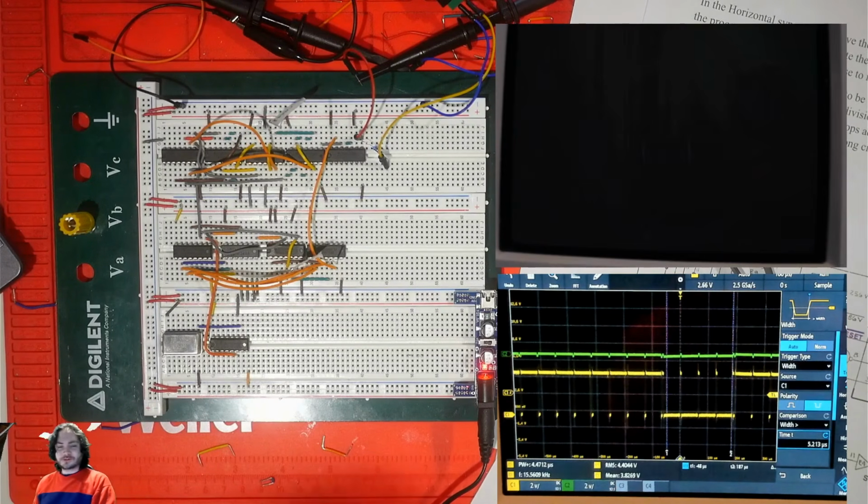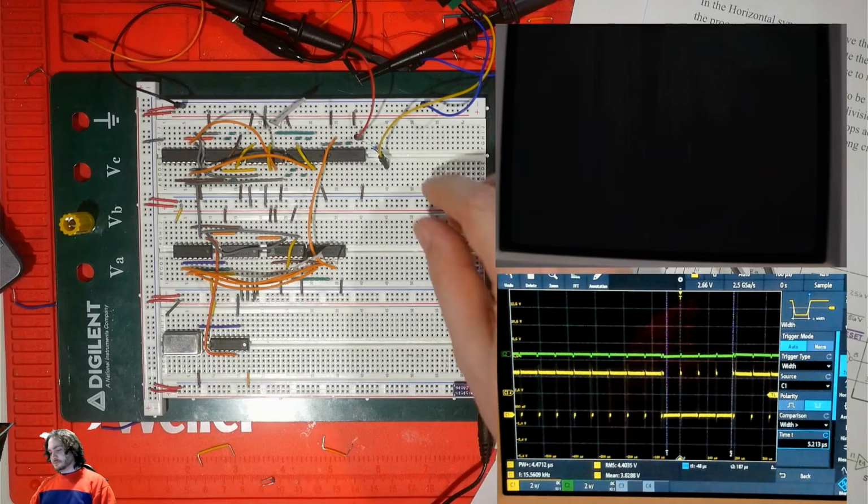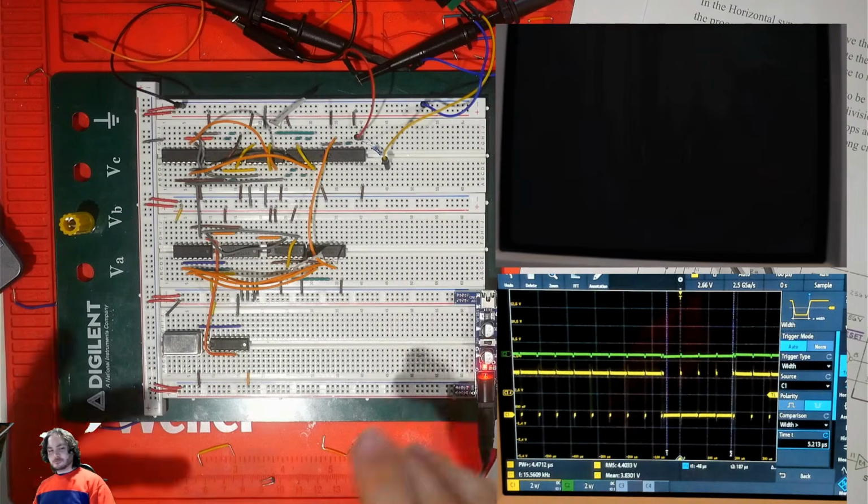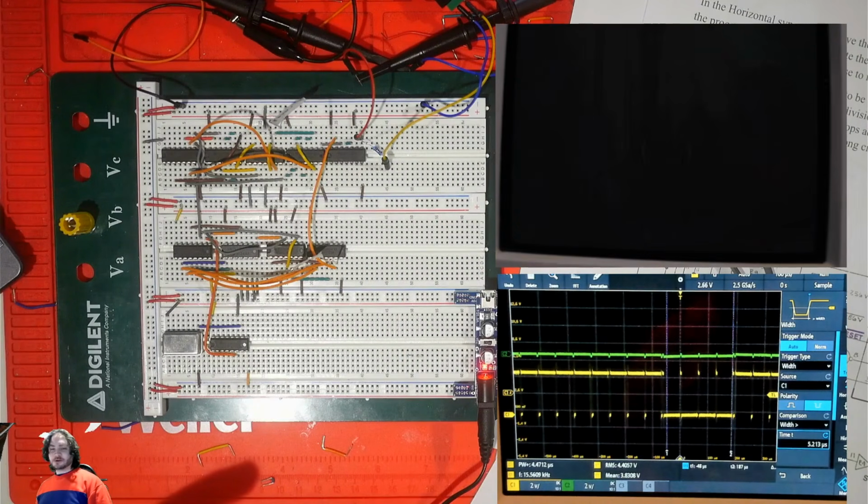Now visually, of course, nothing is really happening that's interesting because we're not sending any image information. So we're going to want to try sending some patterns. If we do that without regards to the timing of the synchronization pulse, then the image can interfere with the sync and the TV will lose it.